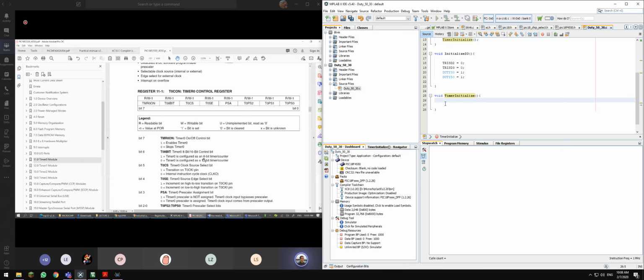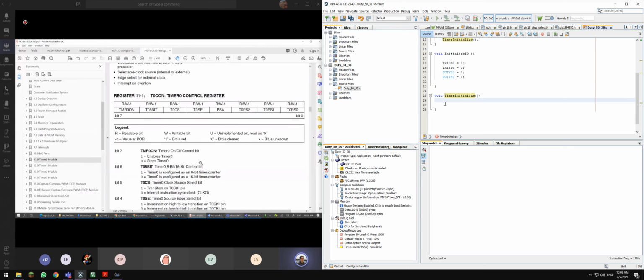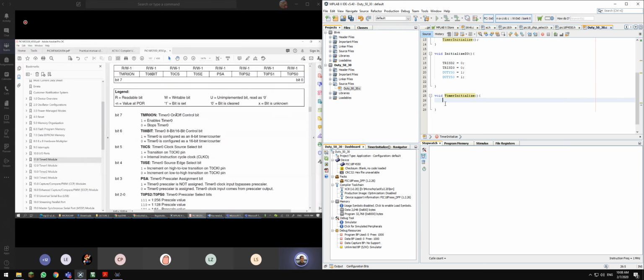So, which bit are we using? We are using 16-bit, because 8-bit is not enough. It's 256, and then your counter will be very large. It's up to you. In order to calculate 1 millisecond, if you're using 8-bit, your counter has to be very large. With 16-bit, so I better use 16-bit.